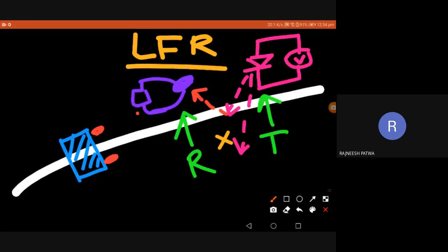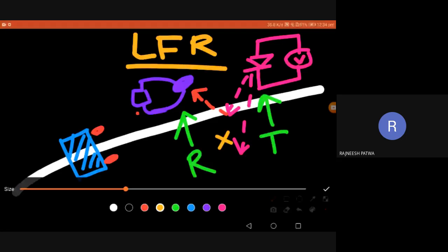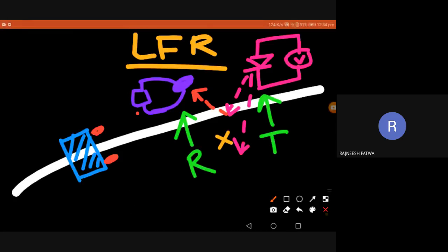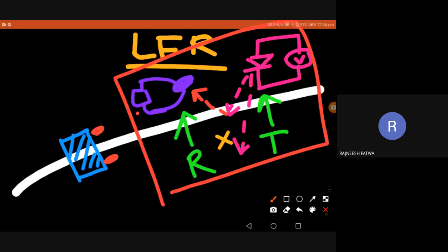Using one transmitter and receiver combined as a single sensor system, what we just discussed, I can consider a complete sensor system. Now I have to place the transmitter and receiver in a logical, intelligent way, so that I can sense whether I am over a white, light surface or a black surface.